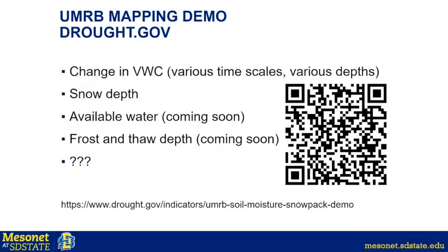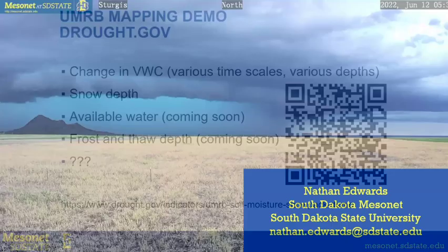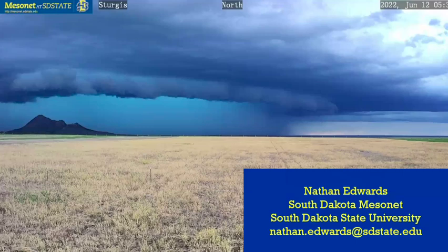To be able to carry over the frozen values rather than just saying, like it was discussed earlier, take a value in November and then carry that over. Things can happen, things can thaw out and then refreeze. So what we're looking at is taking the measurement immediately prior to when it was frozen, and by immediately prior, I mean when it was at 2C, and then carrying that over. It's fairly bulletproof. There's not a lot of things that change soil water content in that regime.